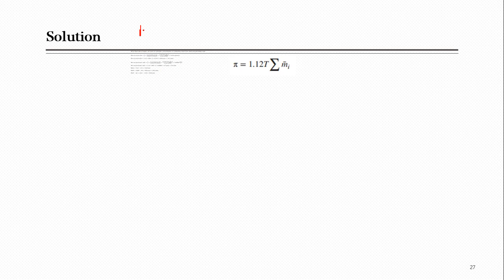That was N of water is equal to permeance multiplied by driving force, and that driving force was delta P minus delta pi. Out of this, permeance is already given to you. Then delta P, the pressure on both sides of the membrane, is given, so this can be easily found.